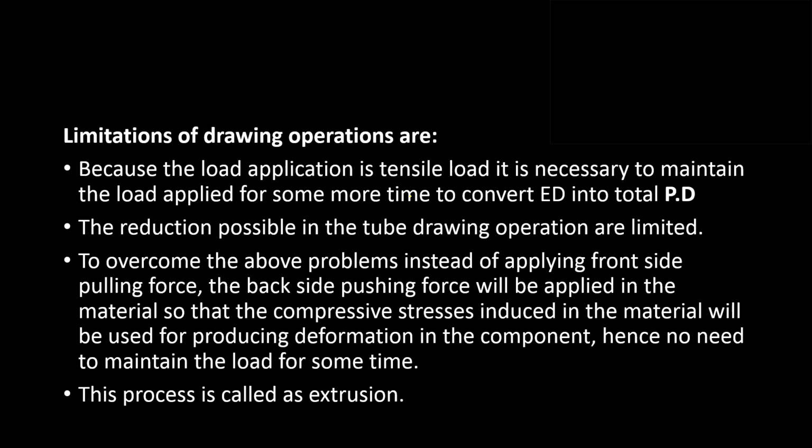So load has to be applied for some more time to convert elastic deformation into plastic. That means the die length will be much longer, and due to that the friction force is higher and power requirement will be high.